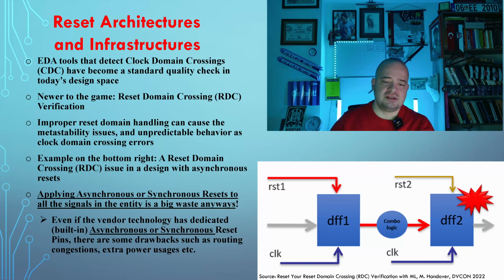It uses one of your lookup table inputs, and it decreases maximum frequency, since it increases total resource usage, and it has routing congestion effects and extra power usage effects. So yeah, you need to make some tables, compare and contrast. You need to check your compilation results, discuss those details with your team, and take your actions accordingly.